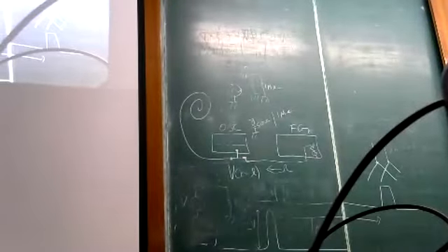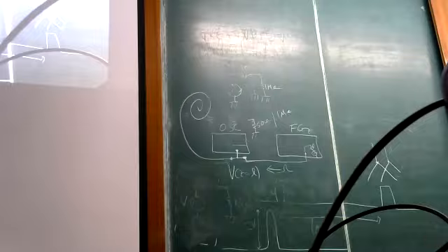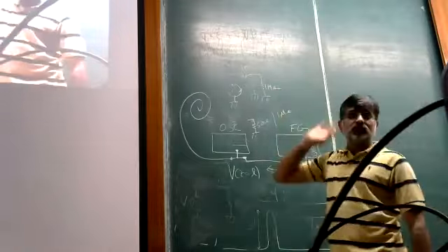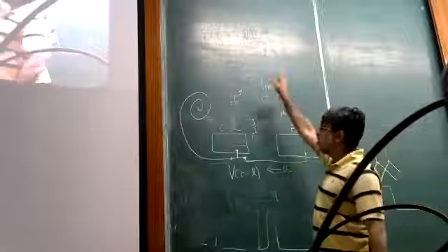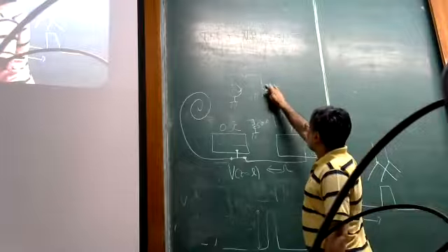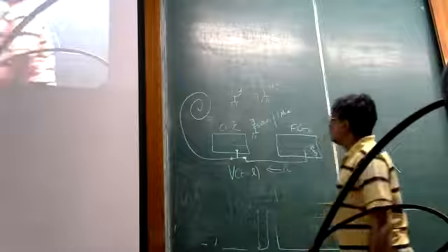So again, the oscilloscope's job is that whatever voltage is dropped across its input resistor, that displays on the screen. That's what it does. So if you calculate that, then you know what it's going to do. So it was 1 mega ohm. Now I'm going to have it as 50 ohms.